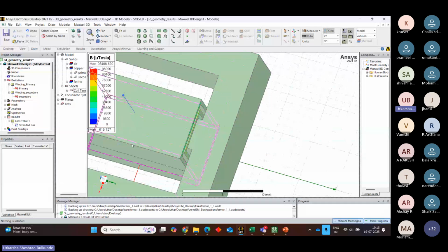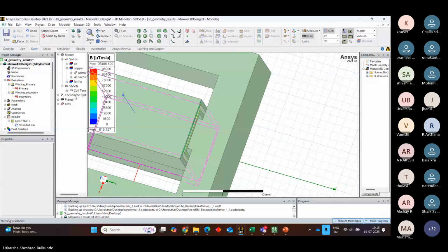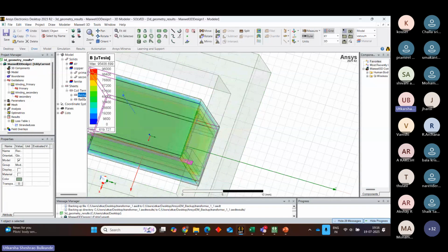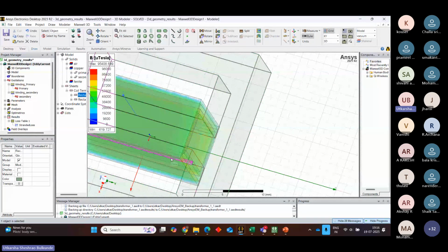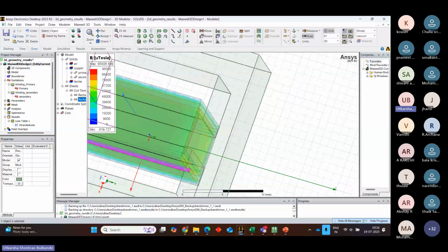So we have put this section here, right? Coil terminal. This section here, right? Do you guys remember now? I told you to give excitation to any solid winding, you have to section it. You guys remember? So here we have put this section with the help of this rectangle, right?